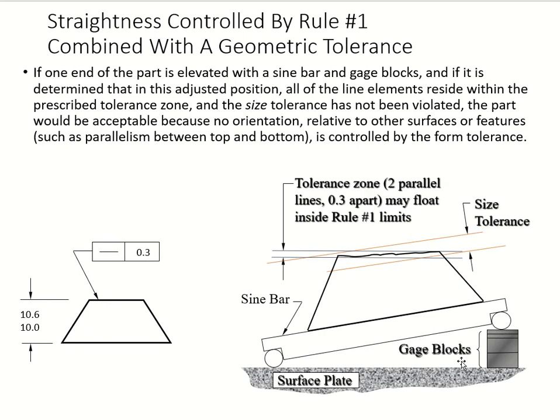Okay, then we're going to bring our gauge blocks and surface plates here. You see the little diagram, how this is just a sidebar showing you the angle, yeah? So here's the Zeiss and here's the tolerance, but the surface is still between, see? That's the Zeiss tolerance. And the sidebar means you have an angle with the horizontal, like you got elevated by using the gauge blocks, yeah? But you see that the surface is within the limit of 0.6, so therefore the Zeiss tolerance hasn't been violated in this example, even if you elevate it.